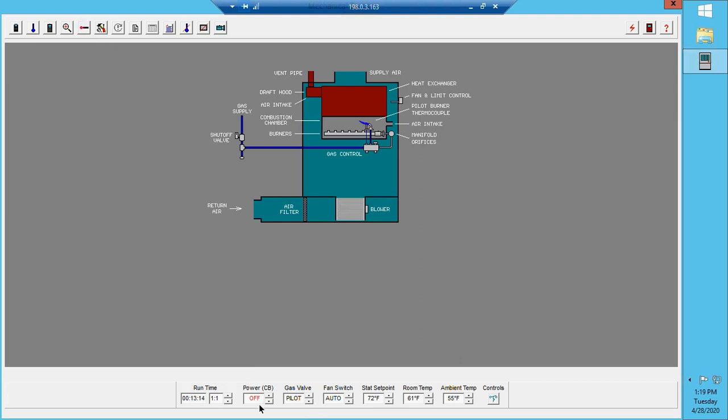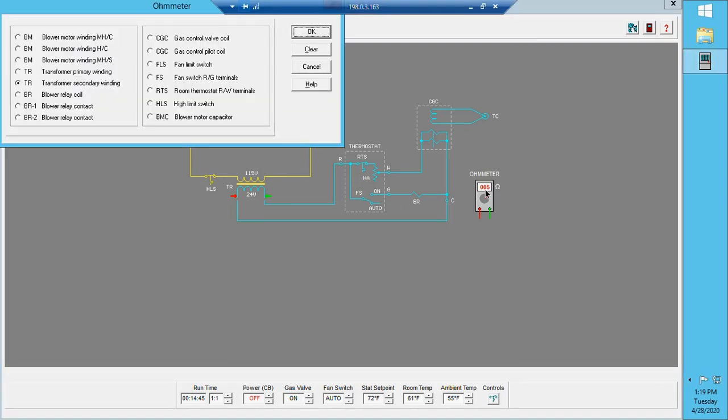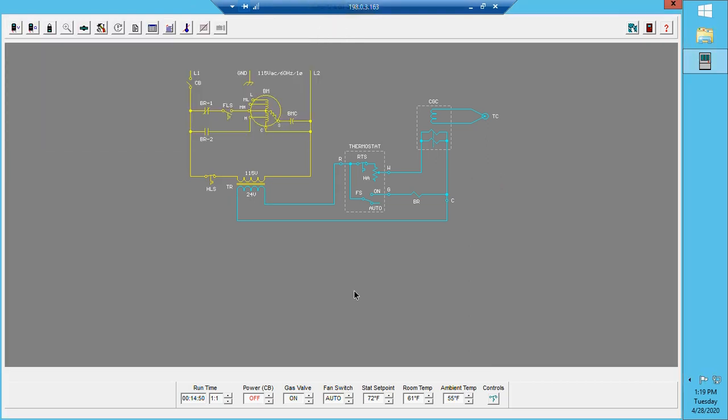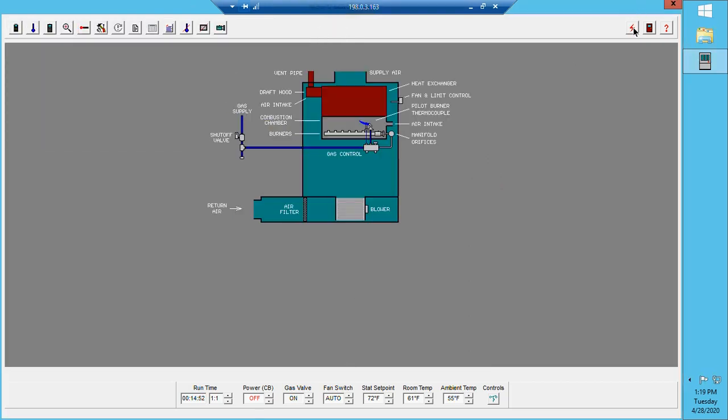So again, we'll go there. Okay, I'm going to raise the runtime just for the sake of not having to wait an entire minute, but I do not recommend that you guys do this. I want you guys to watch this and learn how it happens. Okay, once that has been a minute, I'm now going to turn my power to my gas burner to the on position. Oh, I forgot to do one thing. See what happens? I have to take off my voltmeter or my ohm meter. Now I could turn it on.